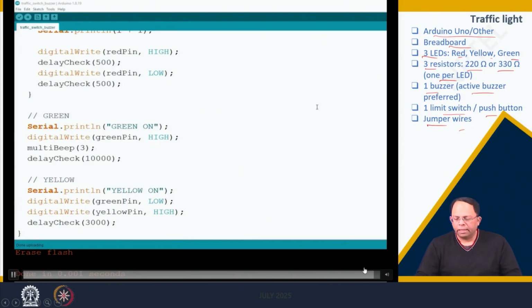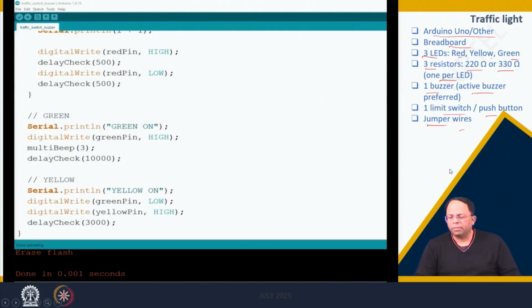And then finally, once we have done that, we will compile the program, and then we upload the program, right? So you can always make some code on your own. Now that you know how to write basic code on turning an LED on and off, you can include delays, and you can create a sequence, and then you can also add checks that if that button is pressed, that function you can include, and you can call as per your wish.